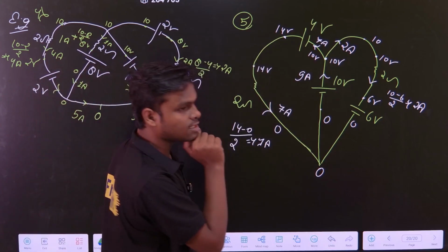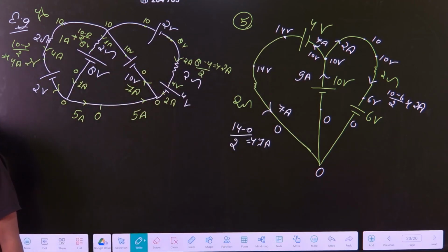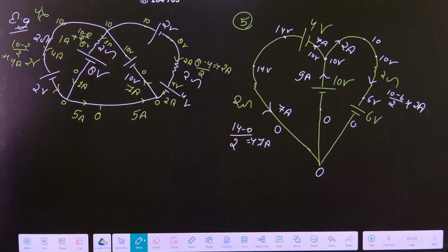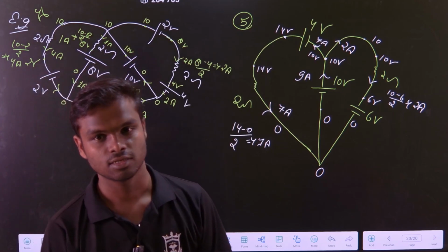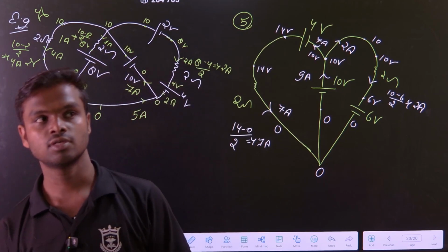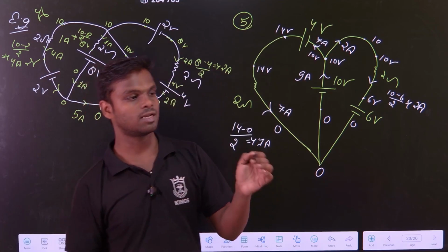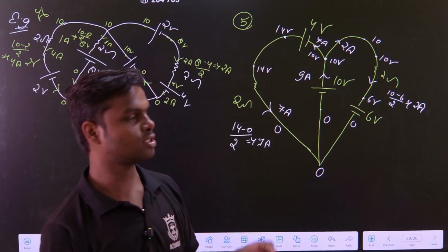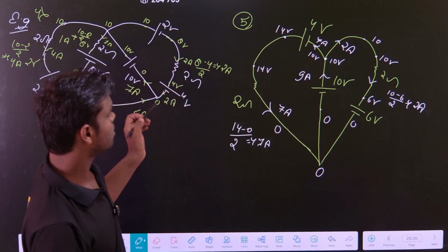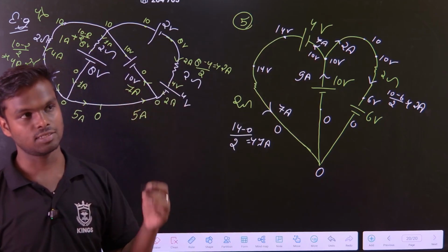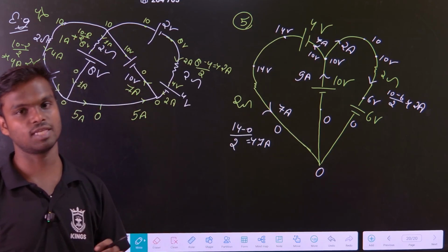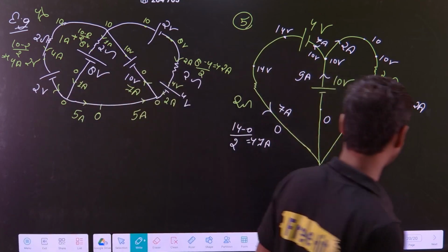Is it clear to you? Till here, anyone have a doubt? Okay, so those are the examples we have seen. To solve any circuit, what do you have to do? Simply take a point and assume it to be 0, and then start. Then I have to simply mark the potential at every point and solve it. Clear? That is a basic simple approach to solve any circuit. Now we will return back to this.